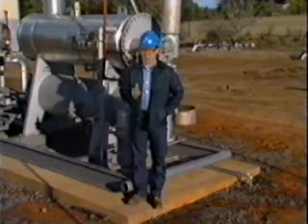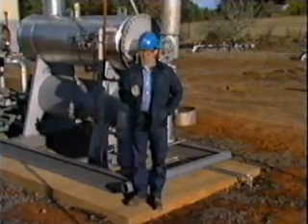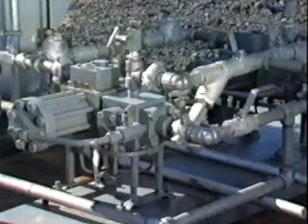Now, there are many types of liquid desiccants used in gas processing. However, in this program, we will only discuss triethylene glycol, or TEG. Now, TEG is preferred in dehydration units because it is easily regenerated due to its high boiling point and other physical properties. It has a high decomposition temperature of 404 degrees Fahrenheit. It has lower vaporization losses than other glycols, and it has lower capital and operating costs than other glycol systems.